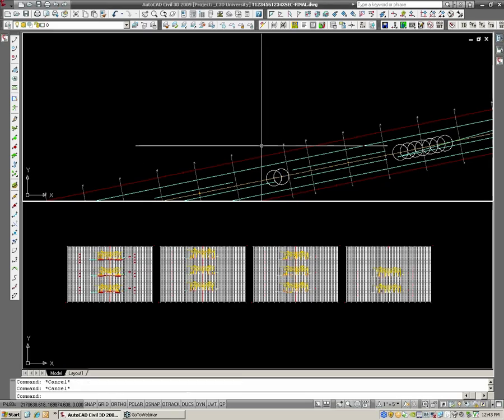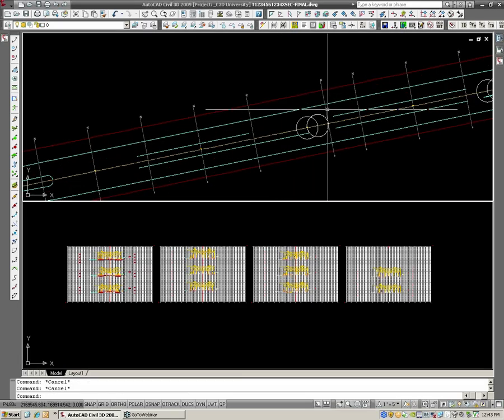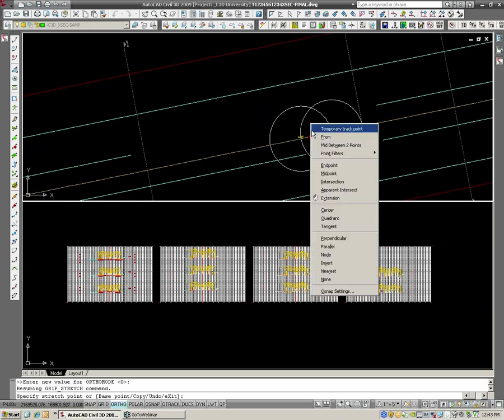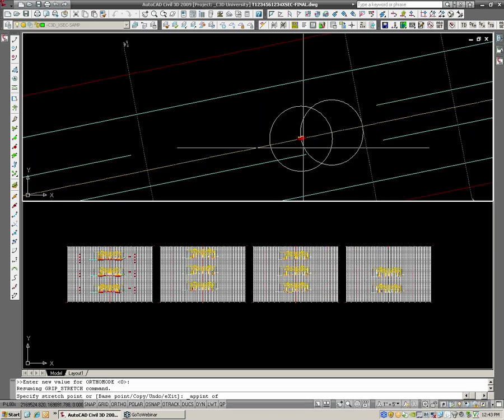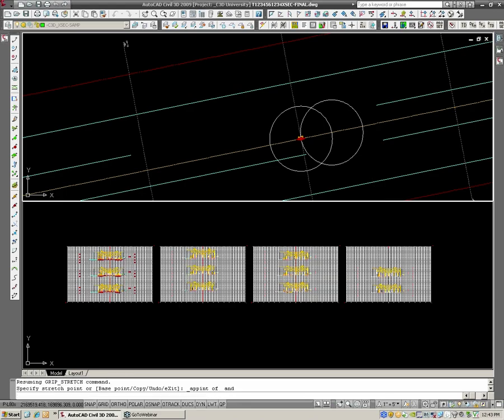The sample line, the corridor frequency, and I think this is what you're getting at, Chris, is independent from the cross sections. In Land Desktop, they were not. If you pulled cross sections every 50 feet, that's the accuracy you were getting.